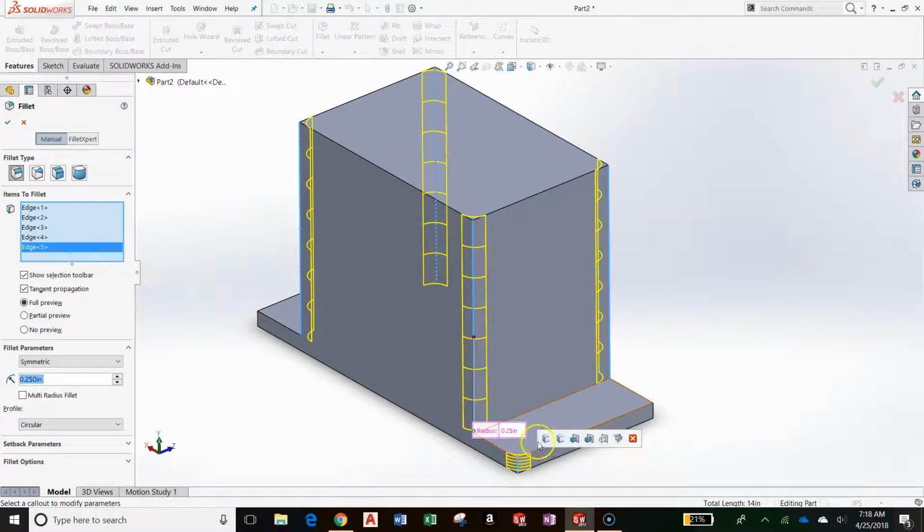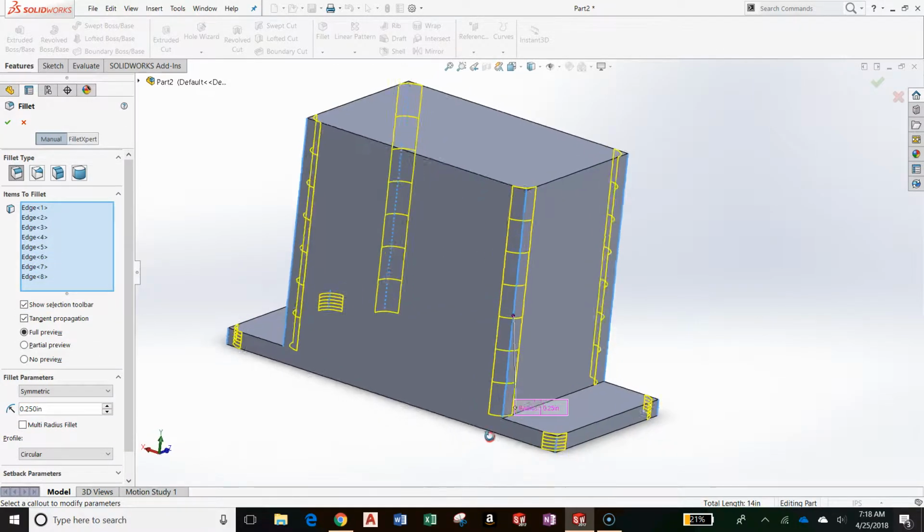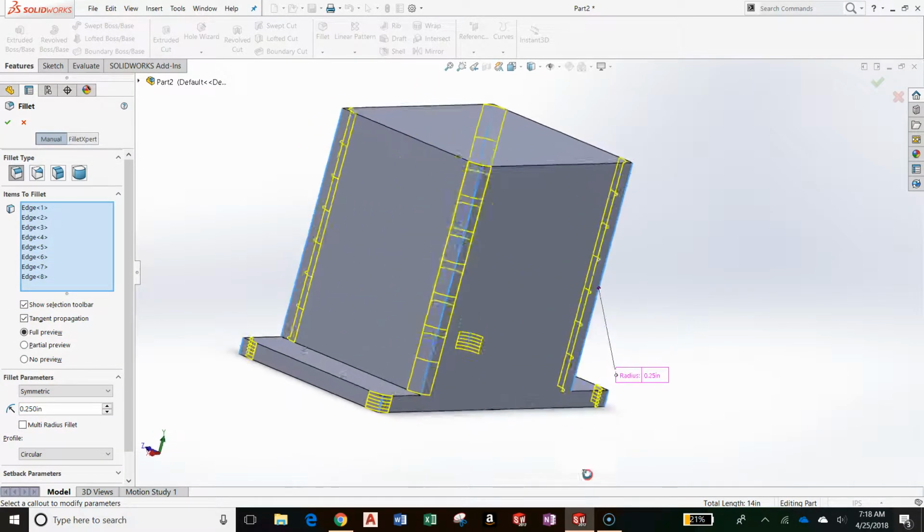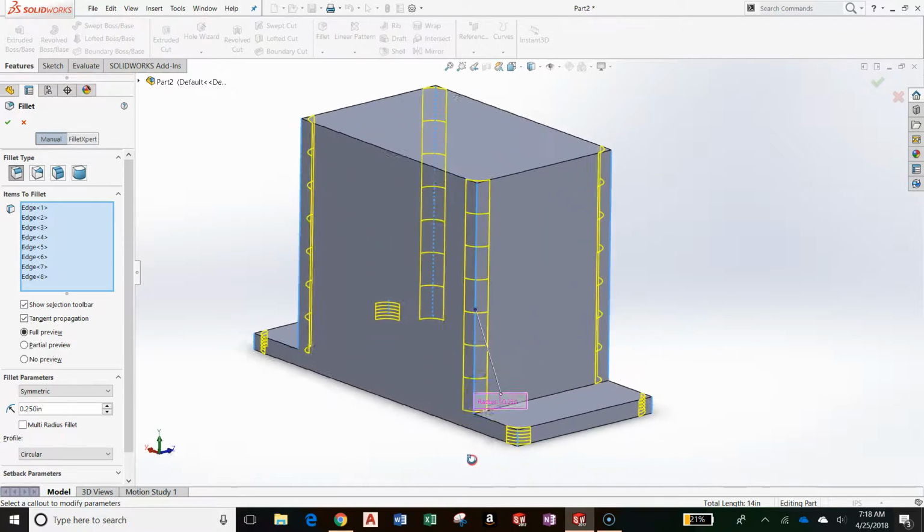So click one corner and then go and click the automatic fillet feature, which on this one it's not going to be the first one, it's going to be the second one, connected to end face 3 edges to get those other 3 corner fillets in there.